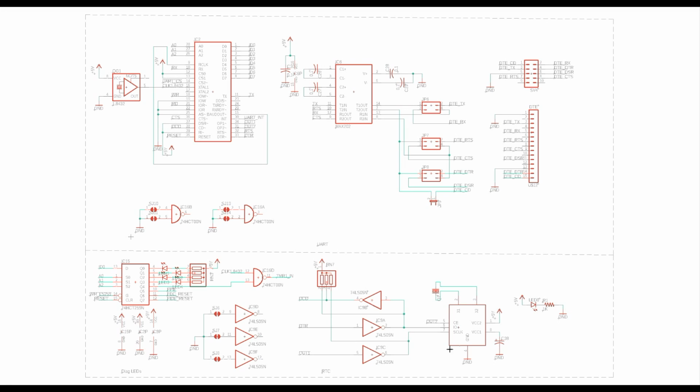There is down here a Dallas 1302 clock. Now I got this from the SBC 188 design, and it's hooked up in a really unorthodox, kind of weird manner here, which I think was for them to reduce chip count. So rather than hooking this up to data lines directly, as they did in one of their earlier revisions of the SBC 188, they used some of the lines on that UART. So they used the carrier detect, the DTR, and 2 of the general purpose outputs. And again, that's just them saving a couple of chips because they crammed a lot into that SBC 188 board.